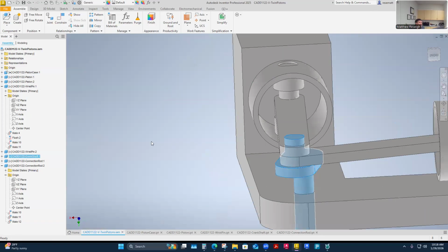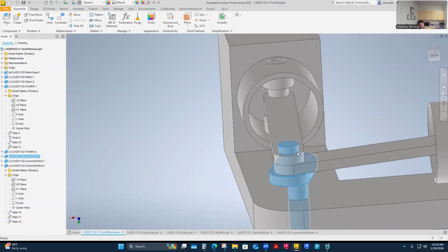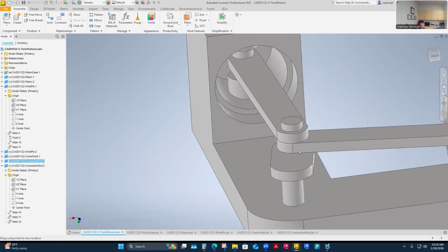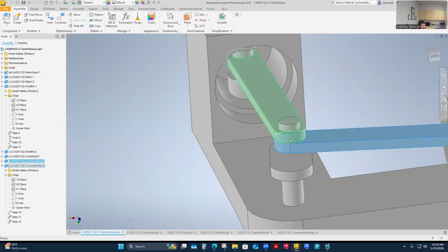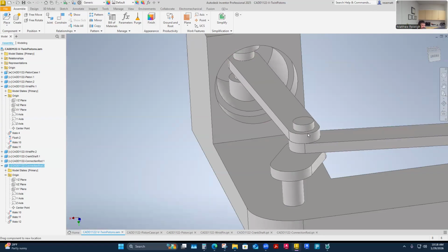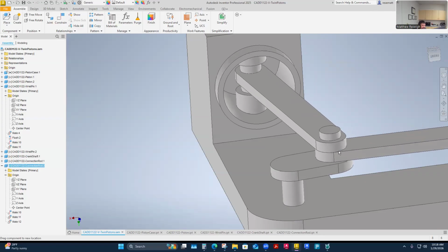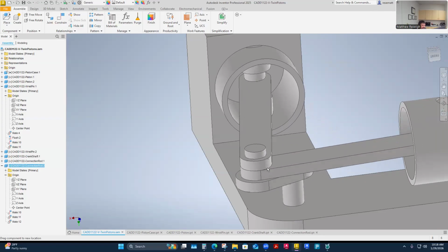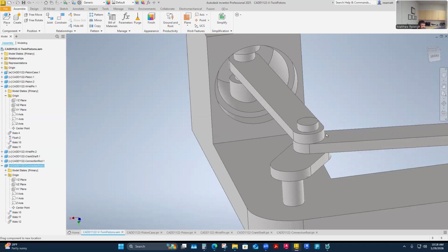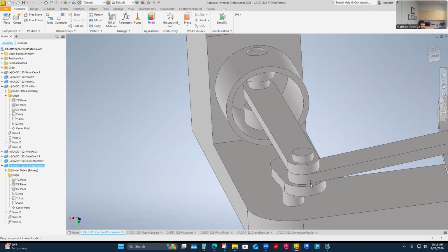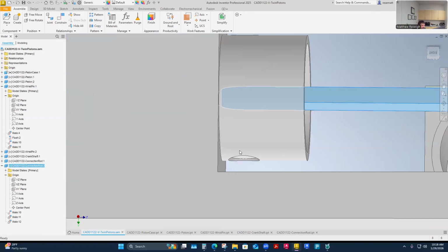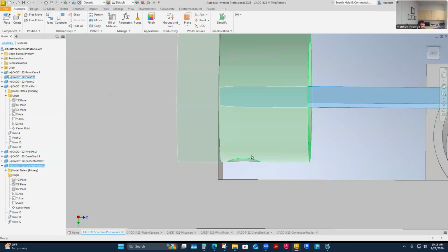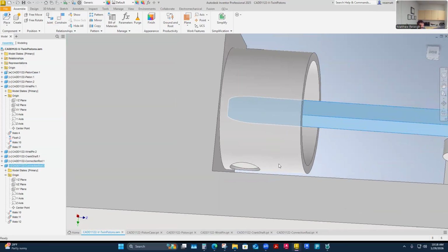So you've got to think about it, unless there's tension, and we don't want too much tension. You can see that this thing has to have some slack, some tolerance, because you'll notice how the connection rods rock back and forth to make that motion. So you can't lock that in. That thing always has to move freely. So we have to have some tolerance on the wrist pin to the connection rod. We don't want the wrist pin to just fall out when this hole is exposed and out of the cylinder door. So I've got to have something that holds that in.